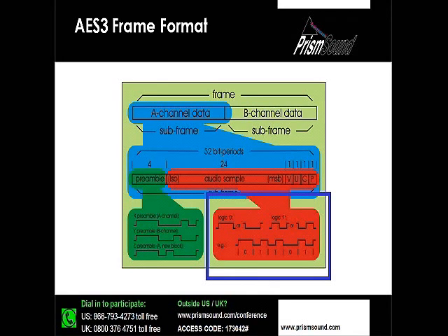And this is interesting in itself and goes way, way, way back to before World War II. But in essence, it allows us to represent zeros and ones, not with high and low states, but with transitions. So we have a bit cell, and in this case, it is a 0 because there is no transition.